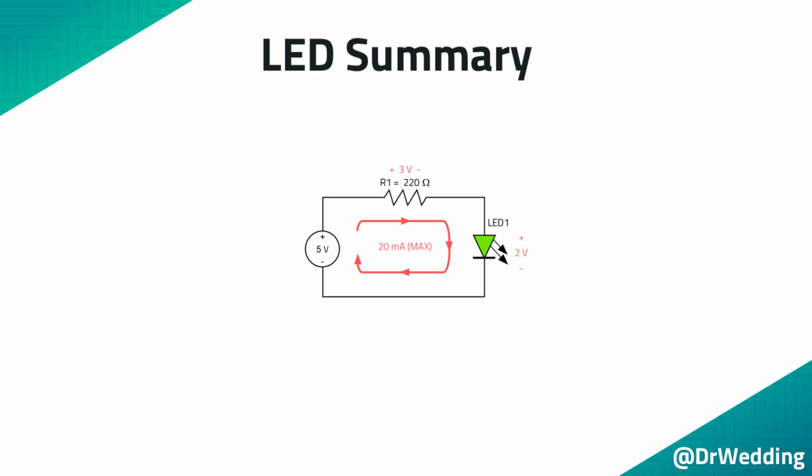Because both of these conditions are met, the equation to find the current limiting resistor value will work and the LED will light up. The LED will have the threshold voltage across it. This voltage is subtracted from the supply, and the remaining voltage is across the current limiting resistor.